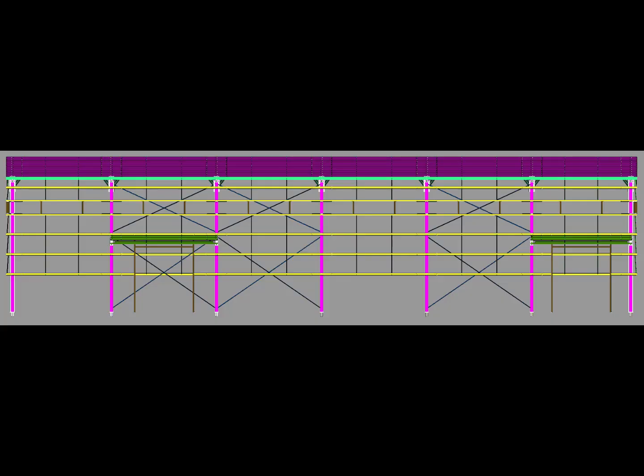If we were looking at this model during actual detailing work, we would need to identify the correct locations of the sag rods and make sure that their connections correspond with the project drawings. This is where the combination of drawing, reading, and 3D modeling becomes very useful. A drawing may show the sag rod using a simple line and a label, but the 3D model allows us to understand where that line actually exists in the physical structure.